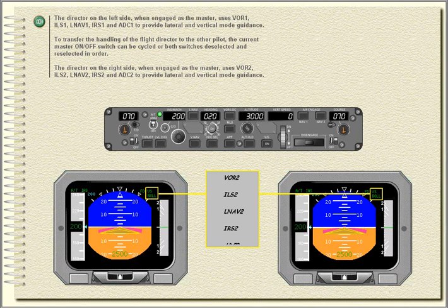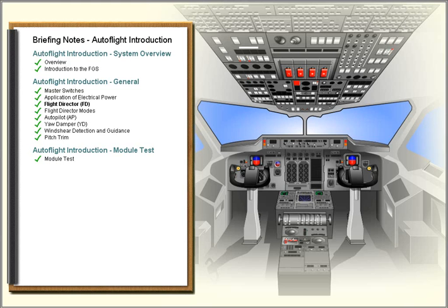The director on the right side, when engaged as the master, uses VOR2, ILS2, LNAV2, IRS2 and ADC2 to provide lateral and vertical mode guidance.